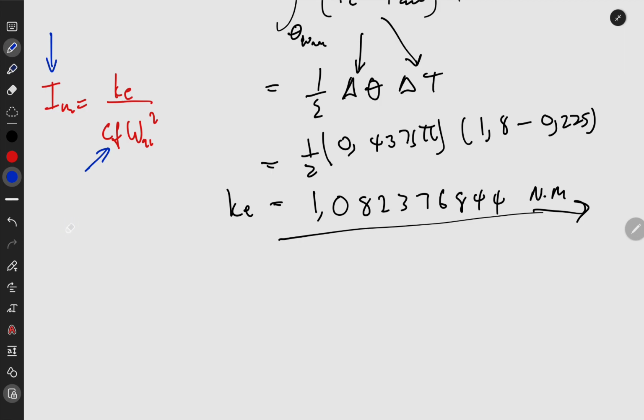Okay, CF is going to equal 2 times omega max minus omega mean all over omega max plus omega mean. So this is a ratio, no units, but now there is more stuff we don't know here. We don't know all these omega that I've been writing. These are the means, and then these are max. Take a difference, then take a sum, then times by 2.